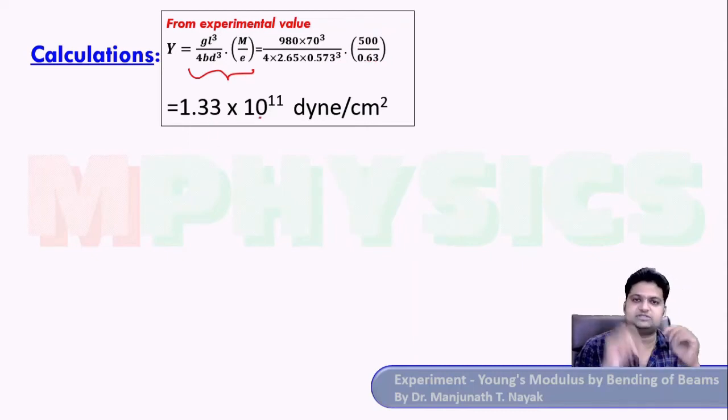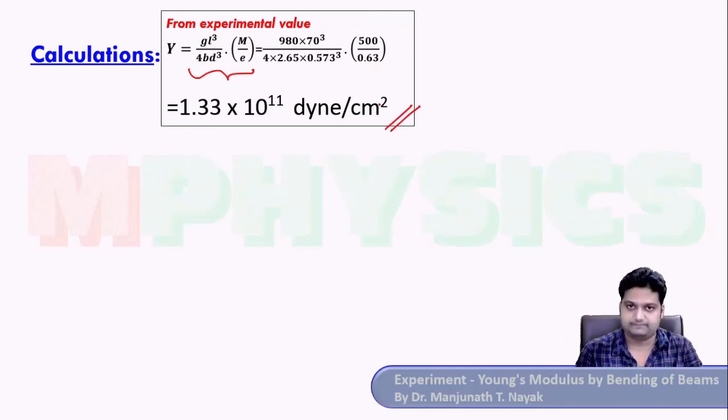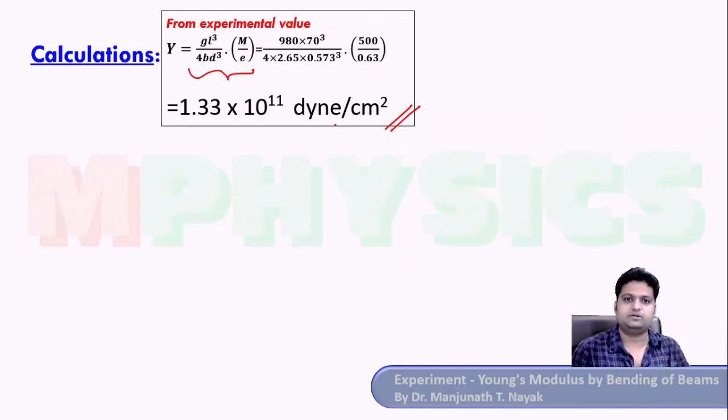Just punch all these numbers on your calculator and cross check. This turns out to be 1.33 into 10 raised to 11 dyne per centimeter square. Very nice value. For wood of this kind, the Young's modulus is around 1 to 2 in these units. So we have got 1.33. It's a very nice value.